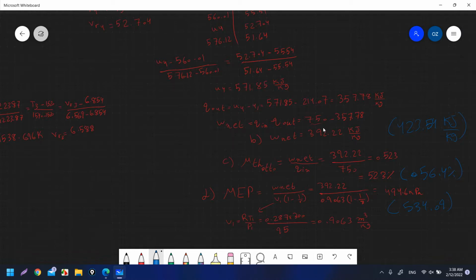Okay, of course P1 and T1 will be different. So you can use either one depending on the question, if it says constant or variable. And if it doesn't mention anything, you have to assume. Okay, variable is harder, or you can say longer, because there are a lot of interpolations. But on the other hand, variable is more accurate than the constant specific heat.